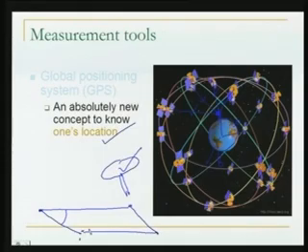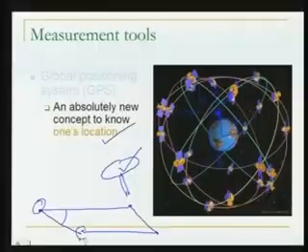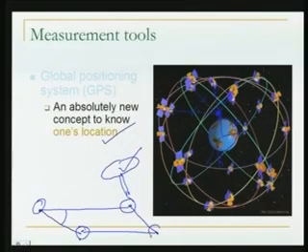So now with a single GPS, as you move, your coordinates are being measured automatically and independently. So you know the coordinates of this point, this point, this point, this point. And if you know the coordinates of all these points, the area of this field is known to you. So it's a very interesting way of carrying out the measurements and a very modern way.